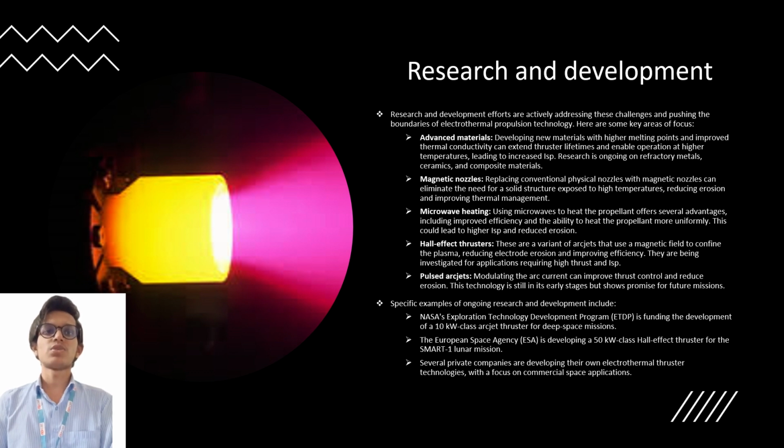The goal here is to develop materials with higher melting points and improved thermal conductivity, extending the operational life of thrusters, enabling them to function at higher temperatures. This involves the research into refractory metals, ceramics, and composite materials, all aimed at enhancing the durability and performance of our arc jet thrusters. Now let's talk about the intriguing concept of magnetic nozzles.